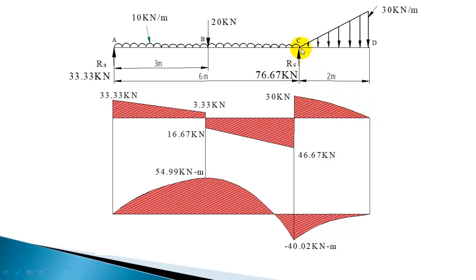So here it's only a gradual decrease, and here when it comes to the major intensity of load, there will be a more sudden decrease. So the concave side should be down when the triangle load zero intensity is on the left side. Otherwise, if the major intensity side is the left side, then you should plot in the other way. There will be a rapid decrease initially, then later the slope will decrease, and there will be a gradual decrease.